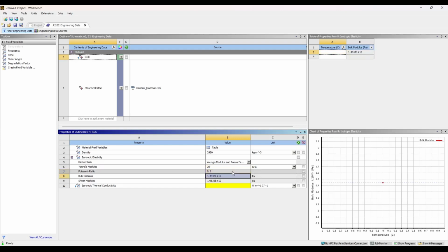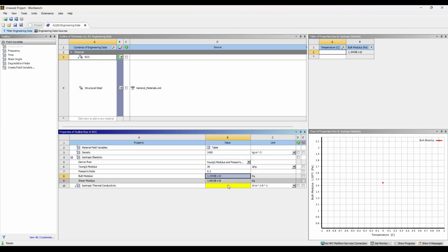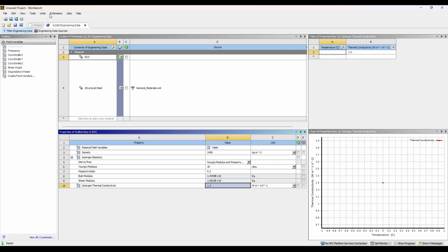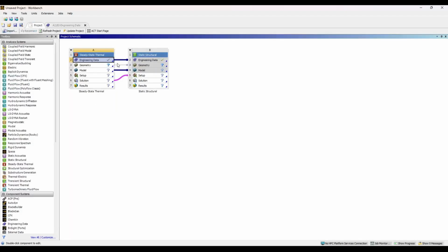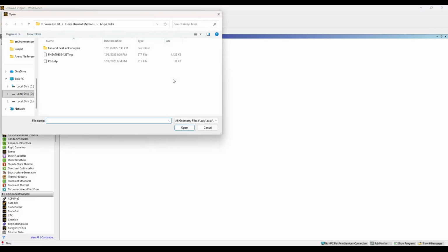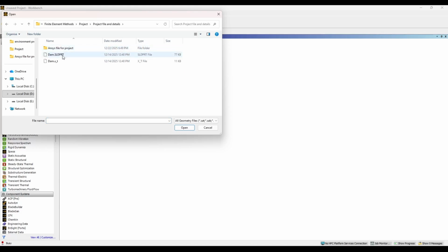Concrete is selected as the dam material, and both mechanical and thermal properties are defined in detail. Mechanical properties such as Young's modulus, Poisson's ratio, and density are used to capture the structural response, while thermal properties, including thermal conductivity, specific heat capacity, and coefficient of thermal expansion, are assigned to model temperature-induced effects. Accurate material definition is critical for predicting realistic deformation and stress behavior.